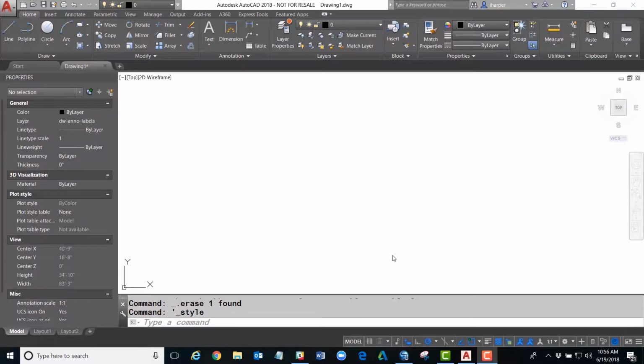Have you ever wanted your annotations to automatically update as changes are being made in your drawing? Well, one of the ways you can accomplish that, depending on the type of annotation, would be through the use of fields. For example, let's say that we wanted the area of a room, or maybe even the lot size, to automatically generate whenever that area changes. Well, we can accomplish this fairly easily with our annotations through the use of fields.